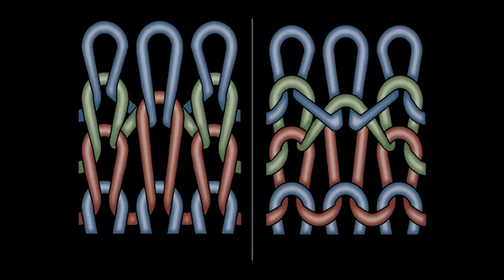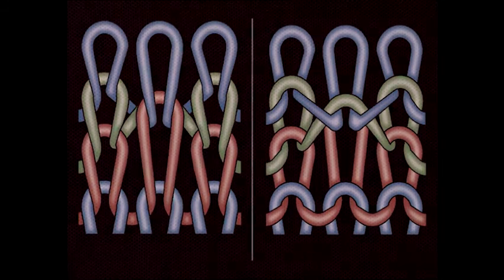Tuck stitches are constructed with an elongated loop and a tuck loop. In this illustration, the elongated or held loop is shaded red, and the tuck loop portion is shaded green. The stress caused by holding one elongated stitch for an extra course causes more length shrinkage, but less shrinkage in width, than a regular knitted stitch. Therefore, addition of tuck stitches to jersey stitches creates fabric that is wider, thicker, and less extensible. The fabric also has more length shrinkage and less width shrinkage.